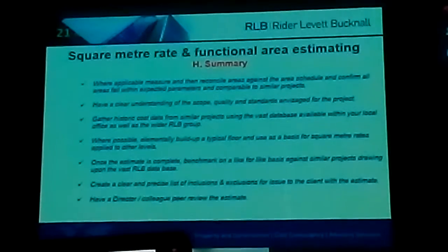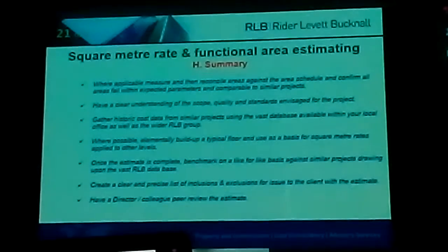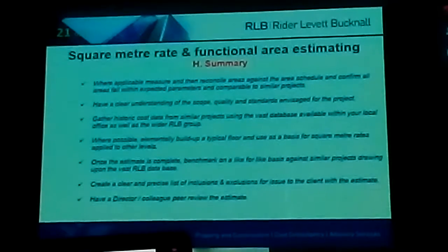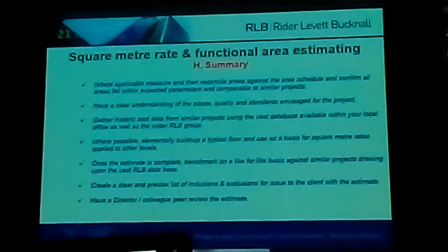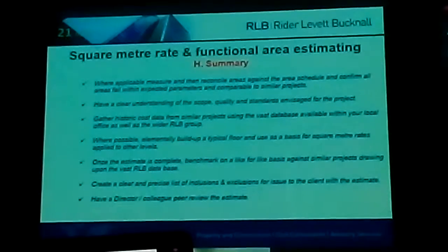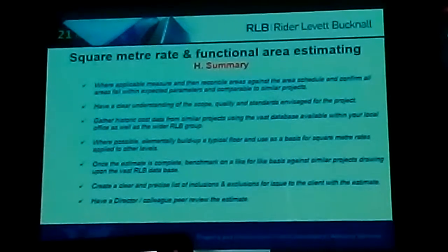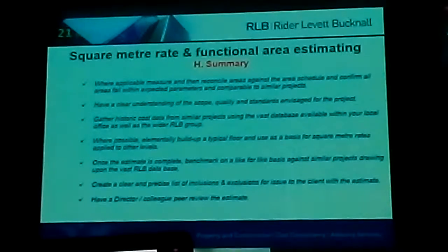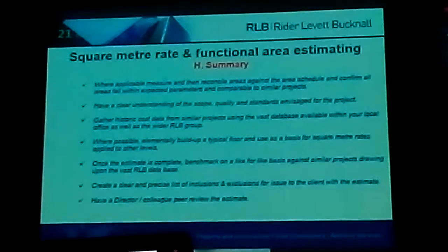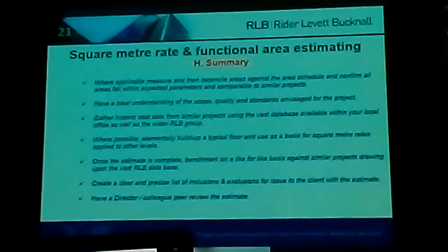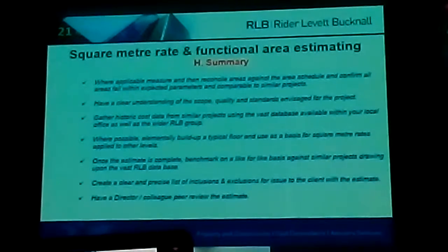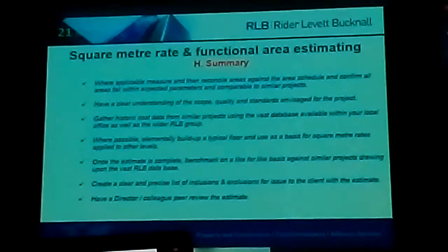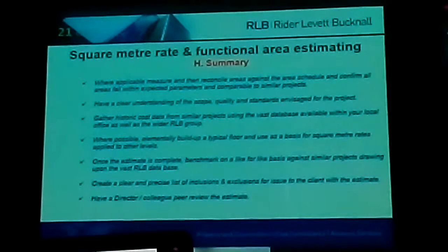Gather historic data from similar projects using the vast database available within your local office as well as the wider RLB group. Where possible, elementally build up a typical floor and use as a basis for square metre rates applied to other levels. Once complete, benchmark on a like-for-like basis against similar projects drawing upon the RLB database. Create a clear and precise list of inclusions and exclusions issued to the client with the estimate. Finally, have a director or colleague peer review the estimate.